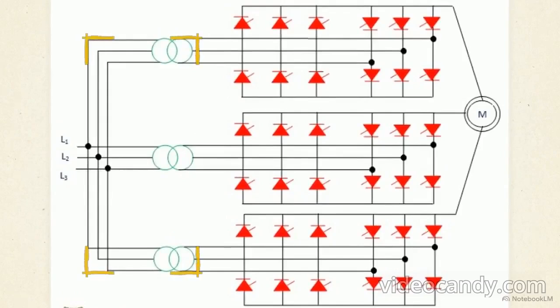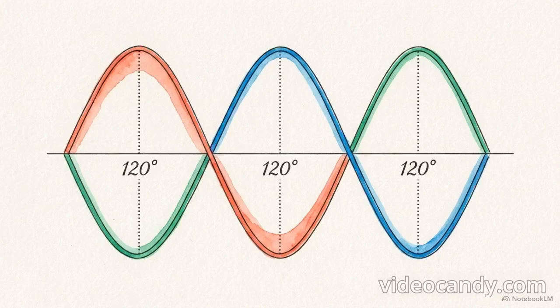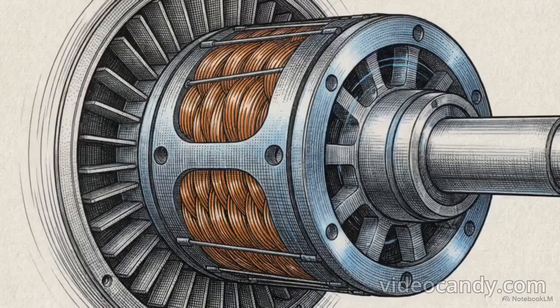Look at this array. To drive megawatt-class motors, engineers construct a three-phase cycloconverter by linking three independent three-phase to single-phase cycloconverters together. The main grid lines, L1, L2, and L3, continuously feed raw AC power through transformers directly into these massive parallel banks of up to 36 individual thyristors. A centralized microcontroller monitors the input grid and the motor load, staggering the firing sequences across all three thyristor groups simultaneously to manage the extreme power demands without an intermediate DC stage.